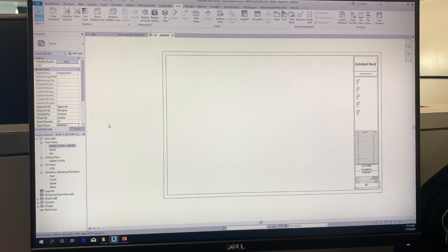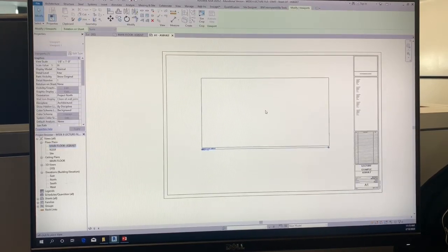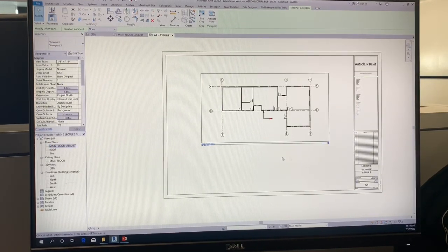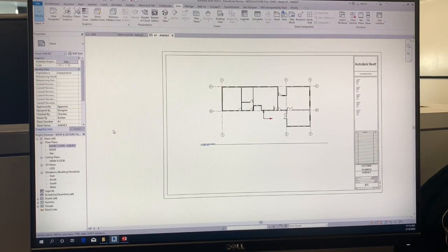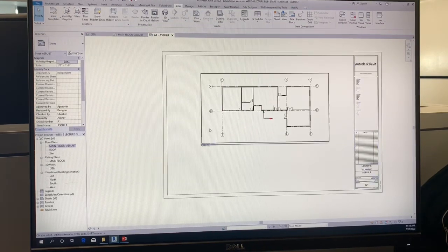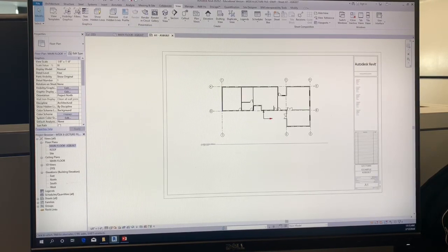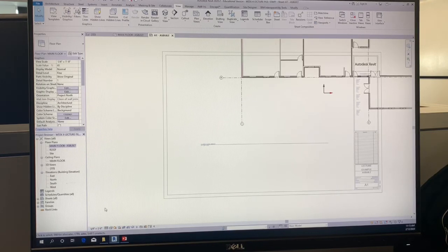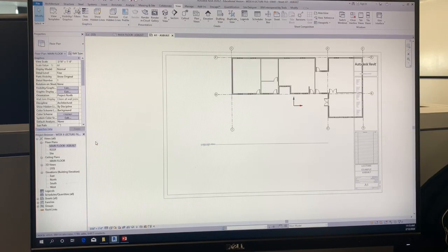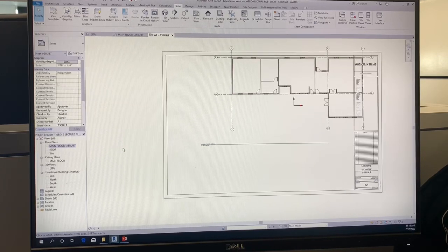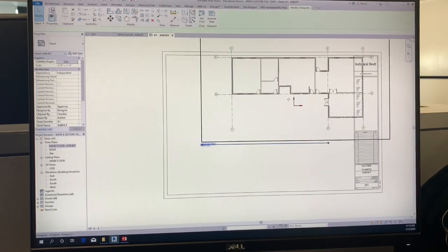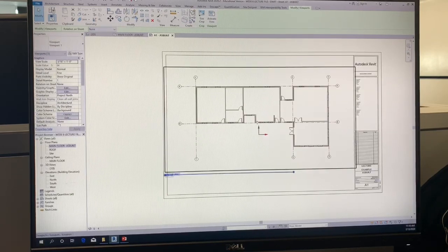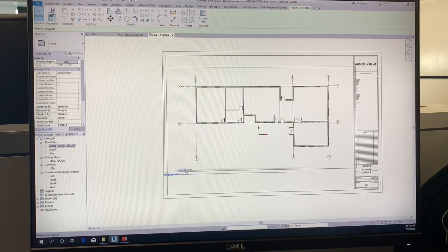All right, so let's go ahead and put our as-built drawing onto this page. Drag it and drop it. There it is. Now, probably that scale is a little bit too small. Double click onto it, and let's change the scale of it. Let's go a little bit larger, maybe quarter inch. Quarter inch is too big. Maybe we go 3/16. That's a good size. So double click into it, change it to 3/16. Double click out of it, and then we'll just center it on our page.